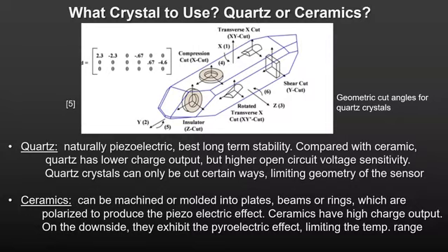They also have very high charge output, compatible with microelectronic charge amplifiers. Ceramics are pyroelectric with a relatively high temperature coefficient compared to quartz. Other than for some expensive and highly specialized ceramics, this limits their usage to smaller temperature ranges than for quartz.